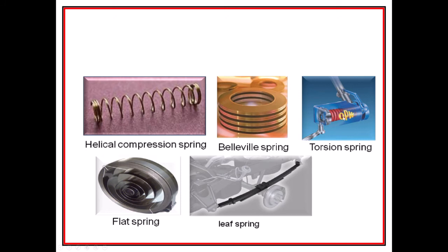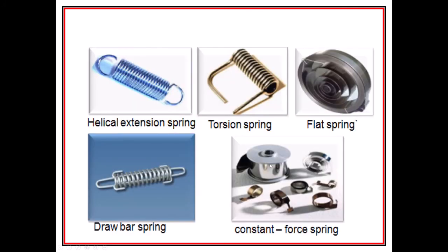You can have a torsional spring, and there are all different kinds of applications where we want to put a torsional spring into things. You have a flat spring. I usually associate these with those little wind-up toys, or a wind-up clock, that kind of thing. And those are energy storage devices. You store up some energy, and then it releases it slowly. You have leaf springs, so there are these flat plates together, and they form the spring that goes underneath the suspension, usually in the rear of trucks.